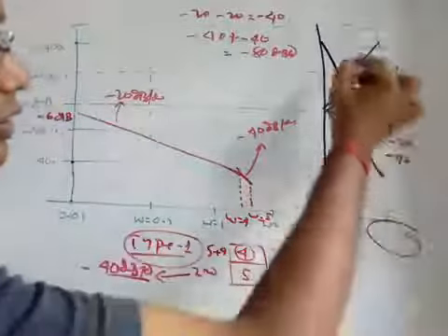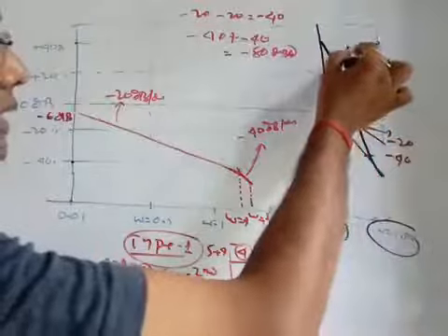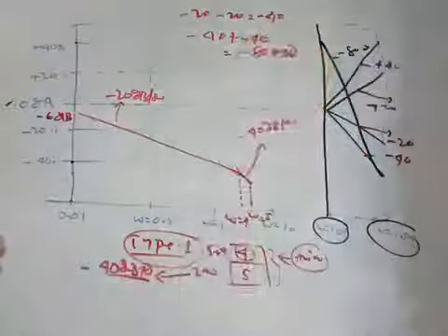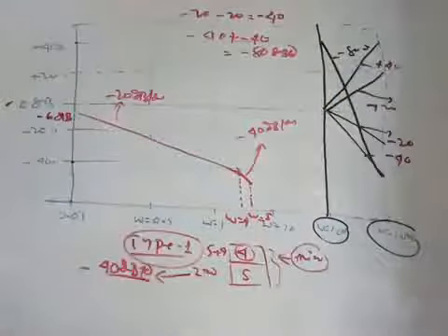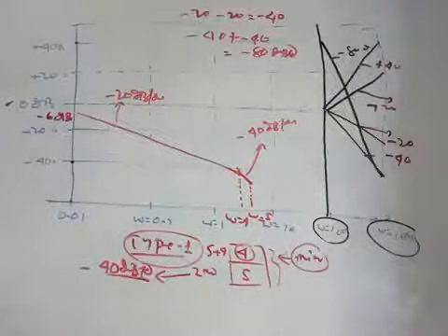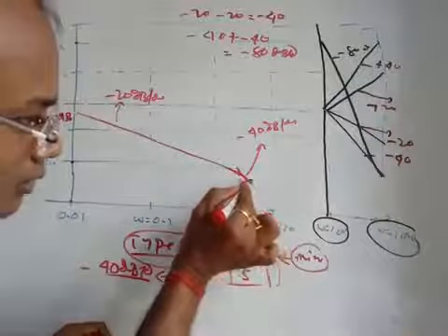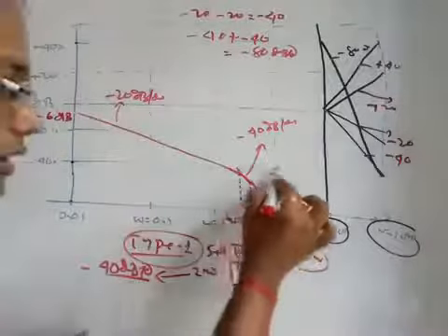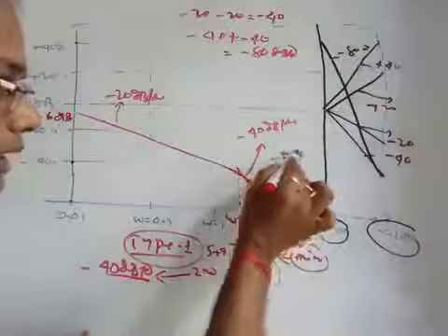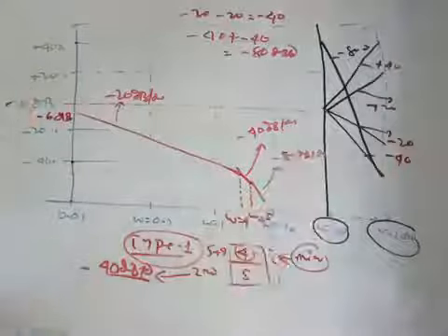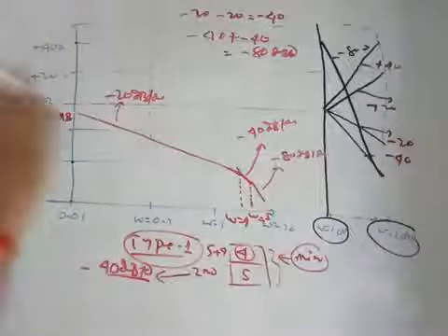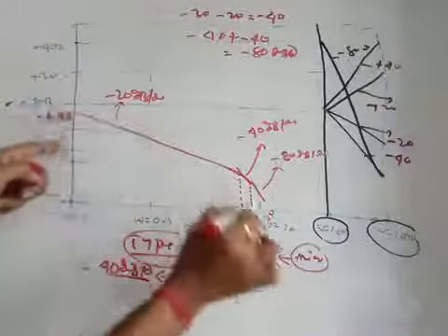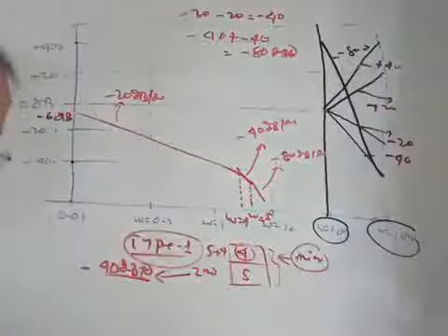so this slope is minus 80 dB per decade, right? So parallel to this line, one slope is to be drawn, right? So you draw a line parallel to this line, and this may be extended after this. So this has a slope of minus 80 dB per decade. So this is, you see, the Bode magnitude plot for the transfer function given.